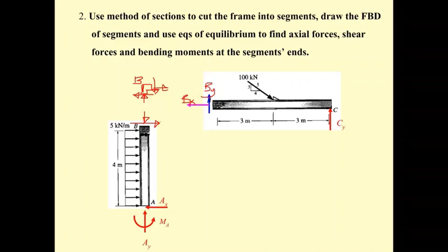And you can see, you may do detailed calculation by putting the column, but you also can skip this and transfer it directly, on the condition that there is no force and no moment acting at that joint. If there is moment or if there is force, we cannot transfer this directly. Okay, let us consider this.